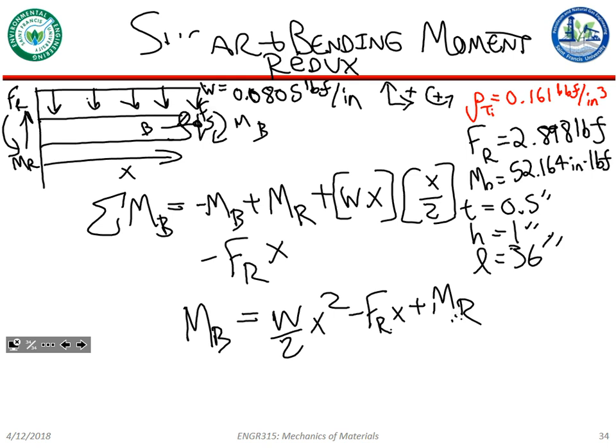If we had a triangular load distribution, that would mean that bending moment would become cubic, because the shear loading would be... Or sorry, no, it would still be quadratic because shear loading would still be linear. Sorry. Anyhow, that's what we get.